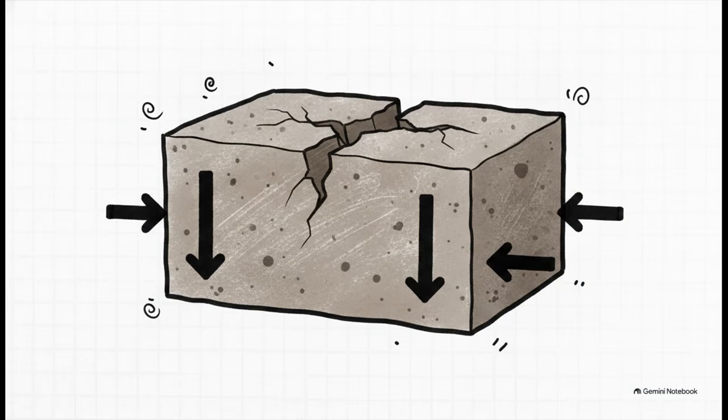That is an unbelievable amount of physical force being generated just by microscopic droplets of water clinging to dirt. So why do we even care about this negative pressure? Well, that negative tension doesn't just hold the water up in the air, it physically pulls on the soil grains themselves. The sheer weight of that entire suspended water column transfers a massive compressive stress directly onto the soil's mineral skeleton. It is literally squeezing the soil together. And this is exactly why fine-grained soils, like those clays we've been talking about, drastically shrink and crack when they dry out or when their moisture levels change.